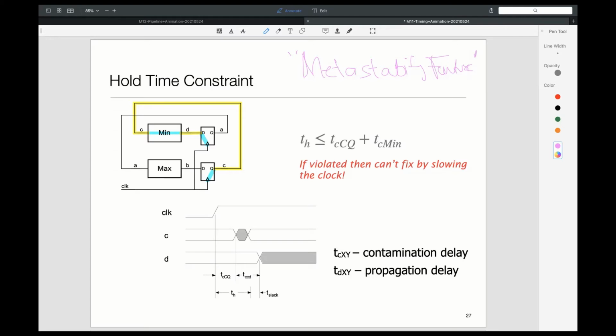And one story that I'm not telling you is that all of these delays are statistical in nature. There's always a probability that, despite all your simulations, your running circuit may violate these requirements. So there's always a tiny probability that a metastability failure may happen in a circuit that you tested at design time. But if flip-flops are well documented, they will have a metastability failure rate, typically like 1 in a trillion years or something like that.